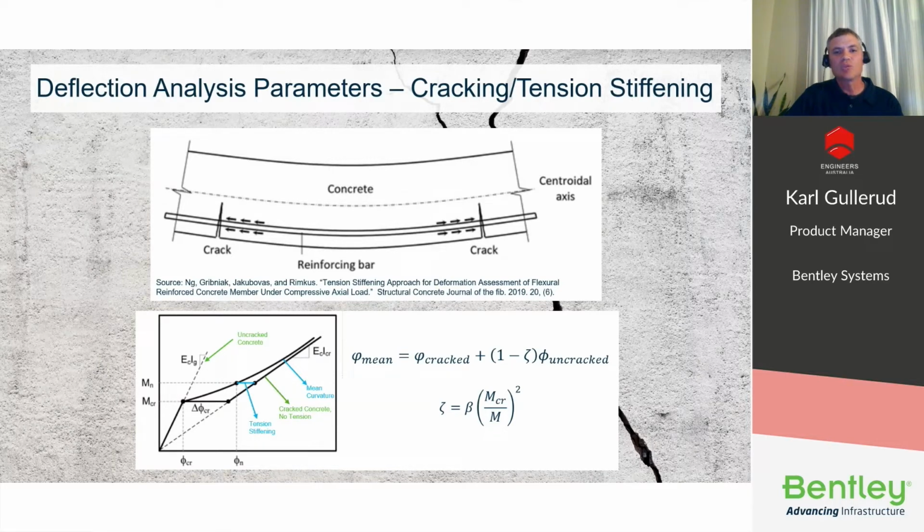This stress redistribution may cause cracks to form in other areas. The behavior then is nonlinear and non-elastic. At crack cross-sections, there is a decrease in stiffness and an increase in cross-section curvature, which leads to increased deflections.